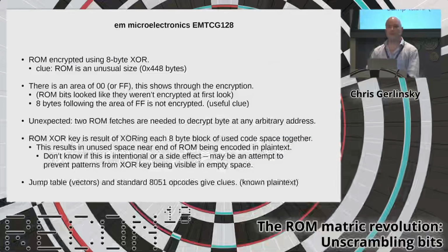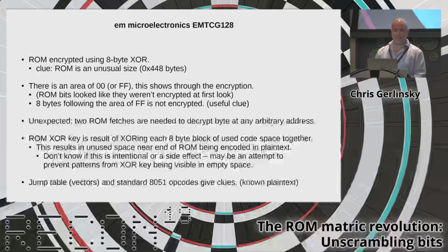So just to review what we saw on this chip, the ROM is encrypted using a very strong 64-bit key, an exclusive OR. There was a clue to that, the unusual size. 448 bytes is a really weird size for a ROM. It's almost always a round number. And so you have an extra 8 bytes for your encryption key in this case.